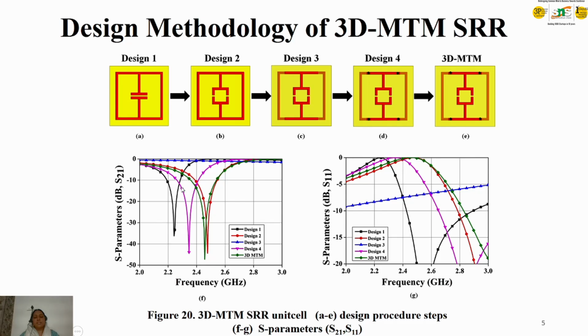The S parameter is calculated for all the design structures, where we assigned a design frequency of 2.45 GHz for our 3D metamaterial structures. The transmission parameter is very good, and the reflection coefficient is near 0 here. We look at the transmission parameters because we are making a transverse wave, where we pass the electromagnetic fields from one port to the other port.